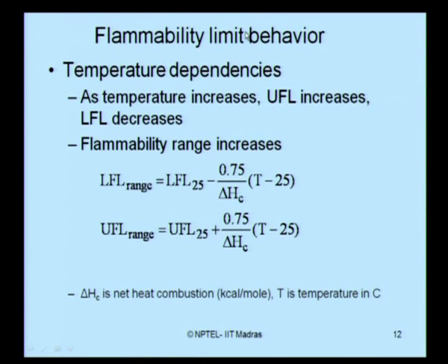The flammability limit also depends on temperature. As temperature increases, ladies and gentlemen, in the previous slide you saw that the upper flammability limit keeps on increasing, whereas the lower flammability limit keeps on decreasing. On the other hand, I can say that the flammability range keeps on increasing with increase in temperature.